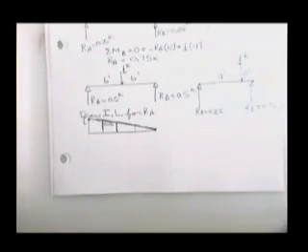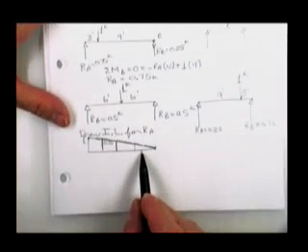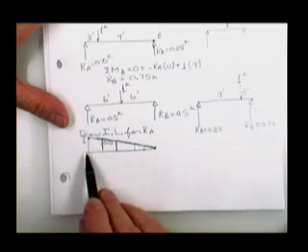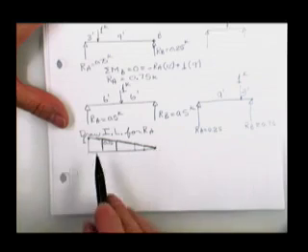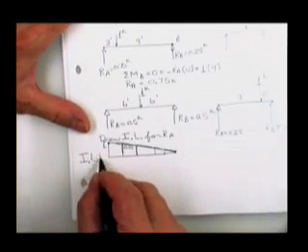It's not a moment diagram. It tells you, when the boss comes and says, if I put the load right here, how much reaction at A will result. In other words, I need the influence of the 1 pound or 1 kip or 1 Newton force rolling across the structure. I need his influence on R sub A.